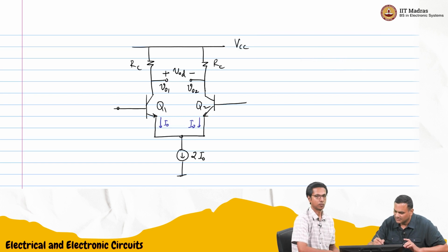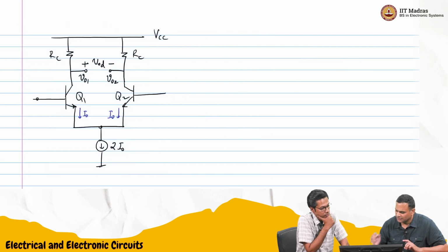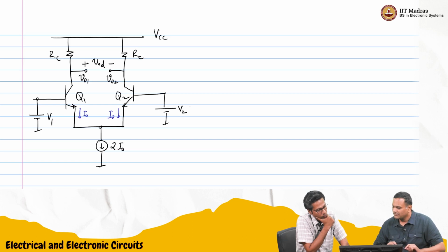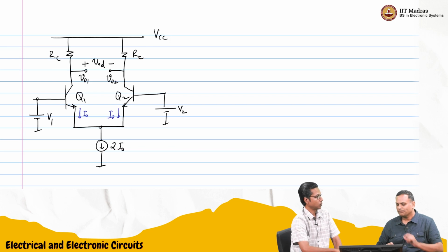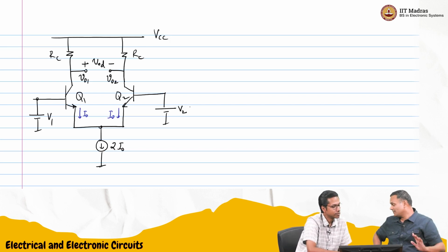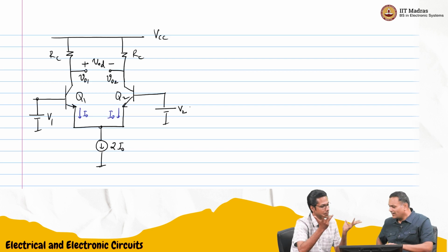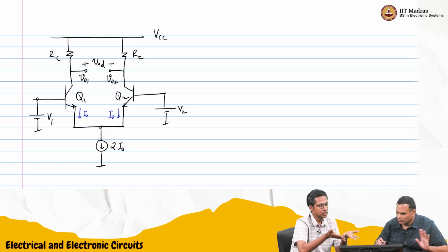Okay, this is the easy portion of the circuit, the core portion of the circuit that we want to look at. So what I am going to do, I am going to connect some DC voltage V1 and V2, and you want to increase V1. If they are same, then no problem. You have current I0 through each side. V01 will be equal to V02. Output is 0.